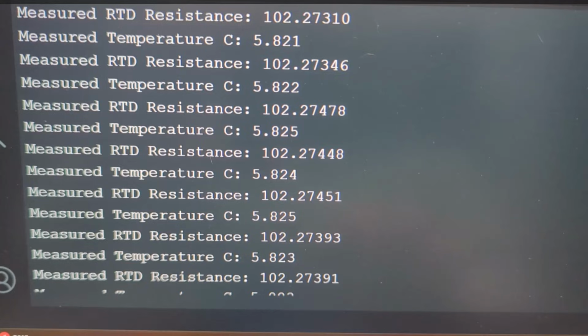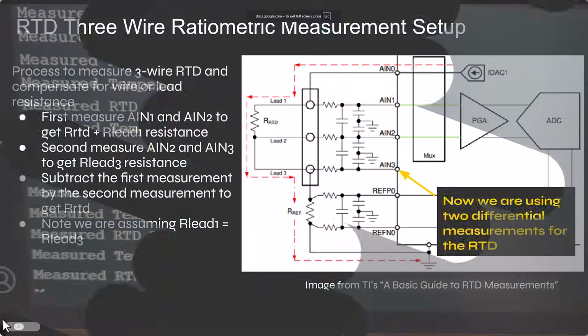So when we did the ratiometric approach, the error came from just the current source and it canceled out. Now we have those two different errors, and if we wanted to make this more accurate using a non-ratiometric approach, we would probably have to measure our voltage reference, measure our current source, and calibrate them in software, have a correction factor to get better accuracy.